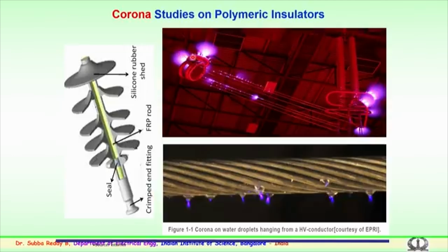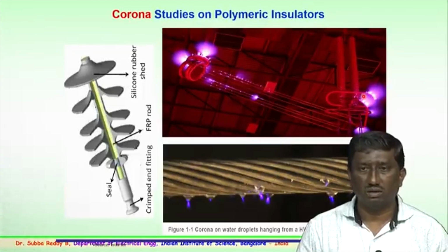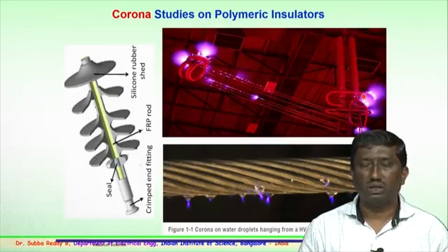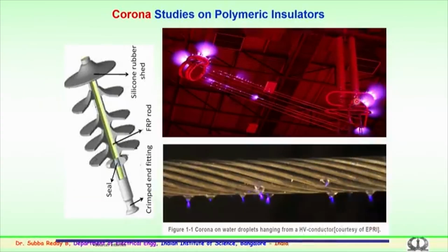Second is the corona control rings. If the corona control rings are not properly designed or not properly placed, this could lead to corona. Here you can see the corona control rings, the corona coming out, and the insulator strings, a vertical double eye suspension. The corona generated from the corona control rings is impinging on the silicon rubber insulators. This has a continuous effect in the field, as the insulators and conductors are energized continuously, and the discharges hit the insulator surface over a period of time. There could be surface damage, or moisture, pollution and other contaminants could make the surface of the silicon rubber hydrophilic, and thereby the water seeps inside the silicon rubber sample and the fiberglass rod may suffer brittle fracture. So, this is the importance of corona.